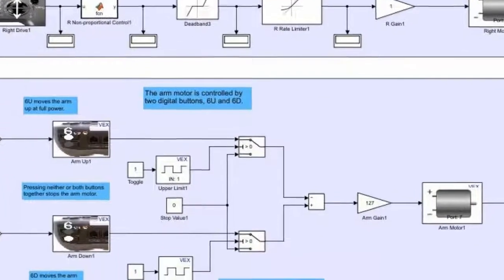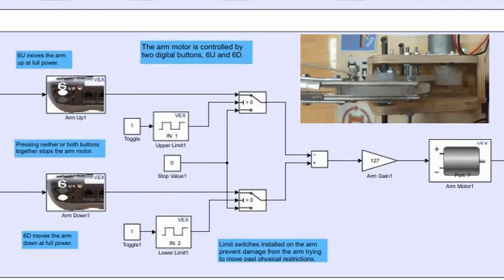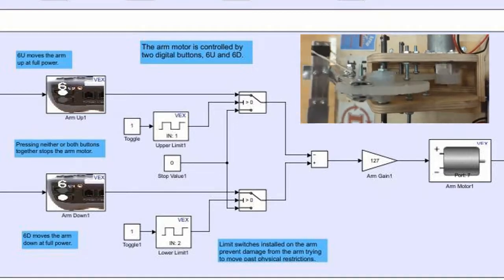The arm is controlled by two digital buttons and two limit switches. This provides simple controls while preventing mechanical damage from driver errors.